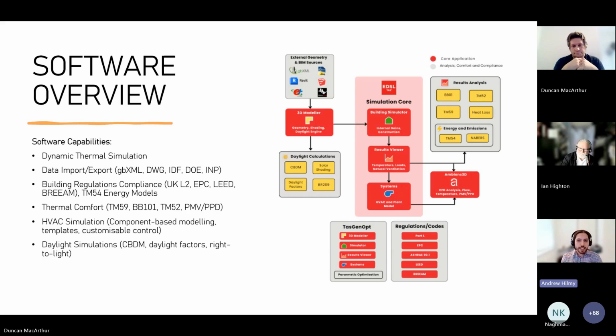Since then we've added things like daylighting and detailed HVAC modeling. And if you were part of our previous webinars, you will have seen that one of the latest things we've done is develop our own CFD algorithms. We've developed something called dynamic CFD, which allows us to simulate a full day's worth of data, which, as far as we're aware, hasn't been done before. This is very tightly integrated with the building simulator, so all the boundary conditions are set off the back of the dynamic simulation. It's quite pioneering and quite fast. We don't use pressure correction like some other packages. We've developed our own validated algorithms, which means our simulation is very stable and fast.